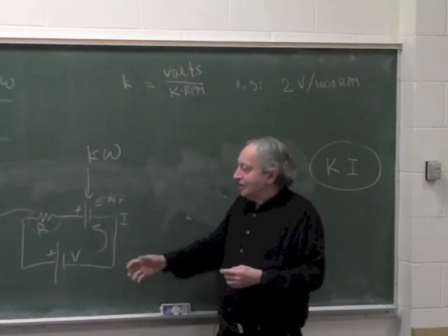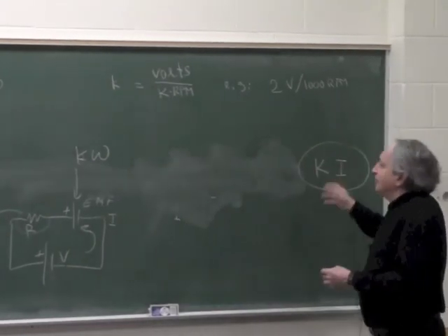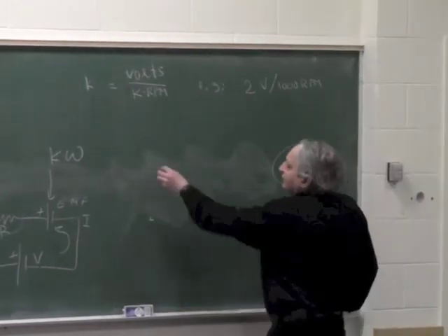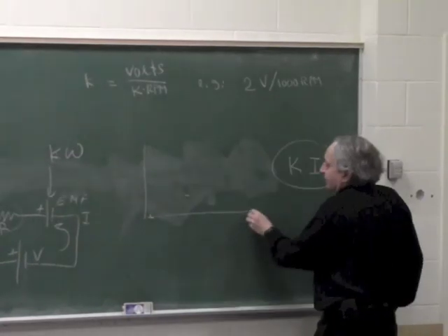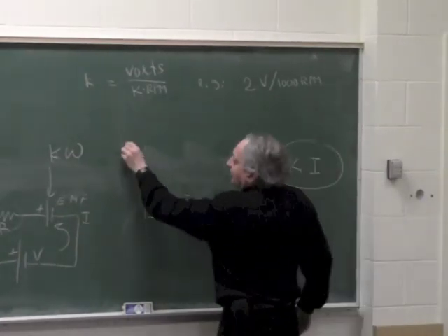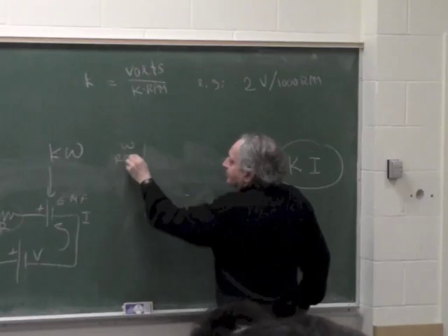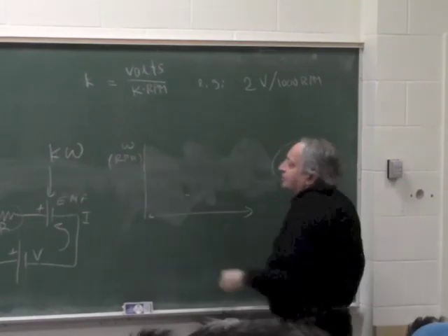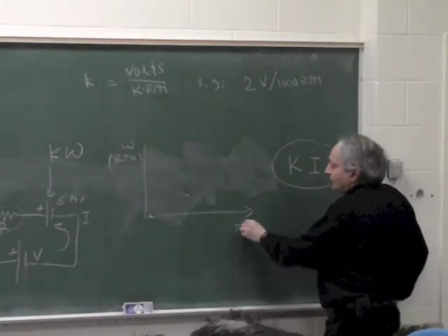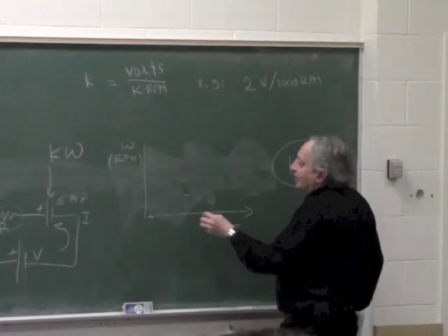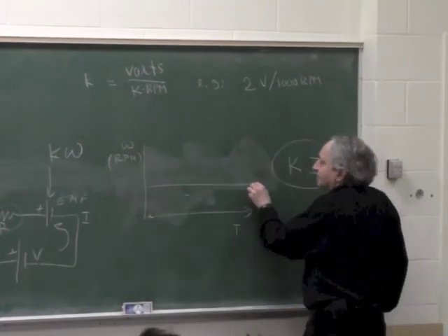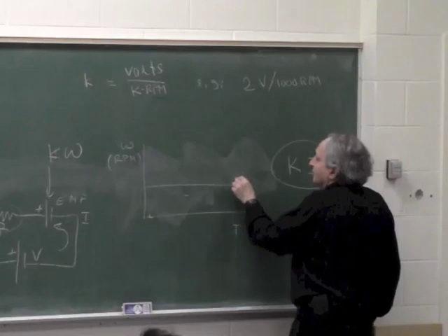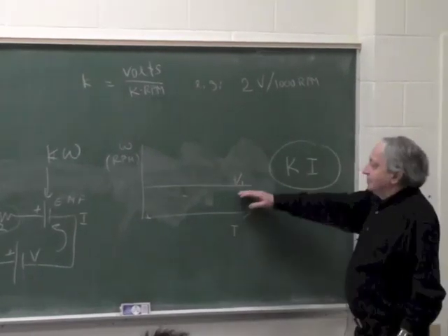Okay? So if they're not equal, current will be infinite, torque will be infinite, it will match. So if I draw now, if this is RPM or omega, which are the same things, just different units, and this is torque, and if I apply V1, I'll get a curve like this. Regardless of torque, at voltage 1, it will have this speed.